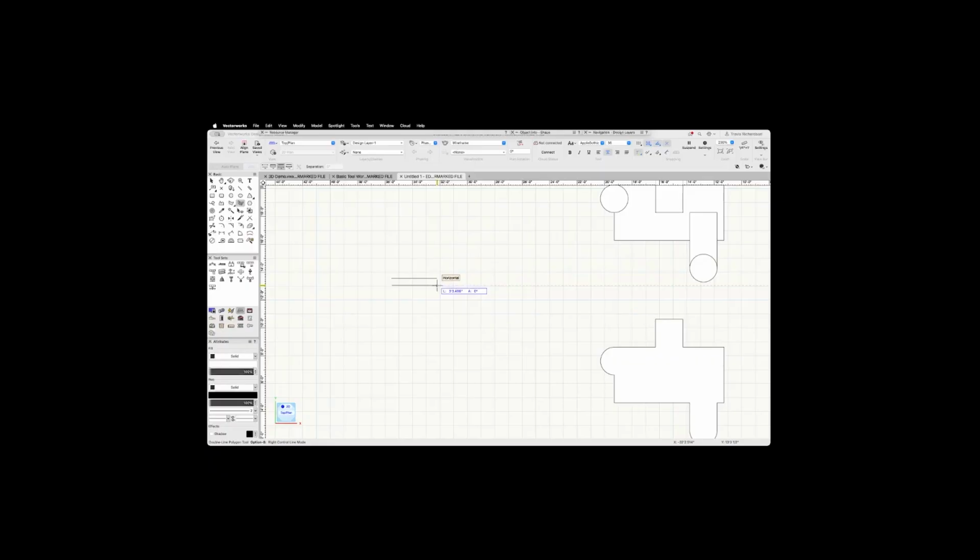So I'm going to tab into my floating datum bar and tell it that I want this to be 4 feet. And I'll click to set that point, and then I'll come down. It's telling me that it's vertical, so I'll tab in again, make that another 4 feet. Click to set that one. I'll repeat that process horizontally. Good. And then I'll do one more at the end to click and complete. And now I have a polygon that actually has double lines.